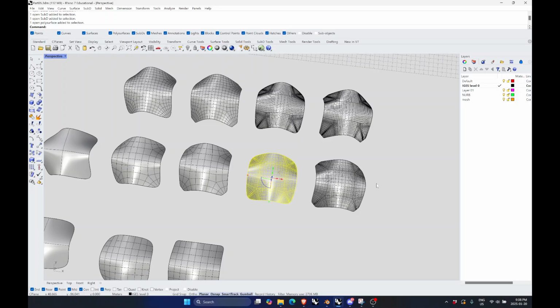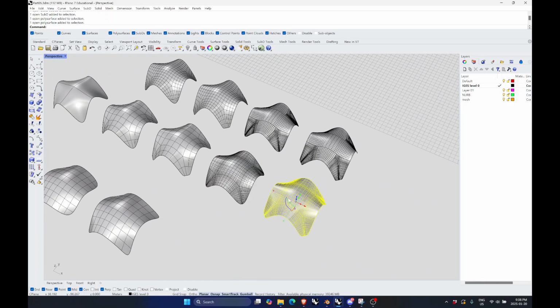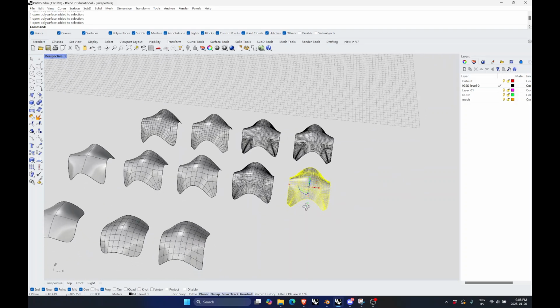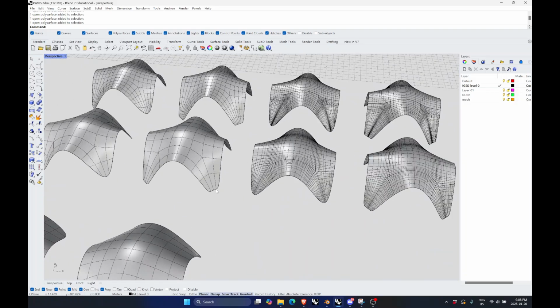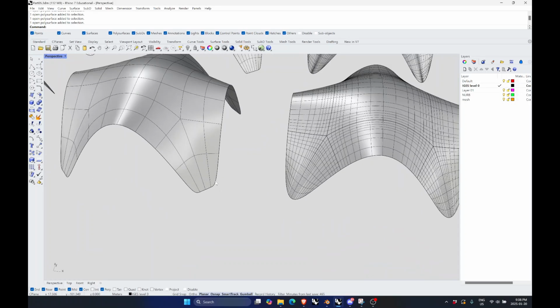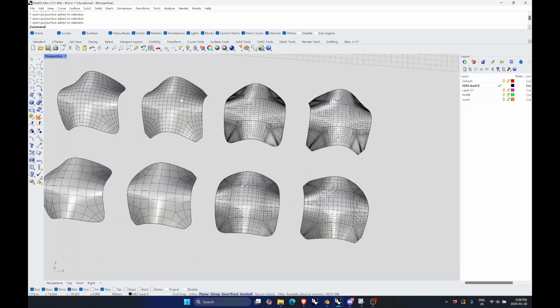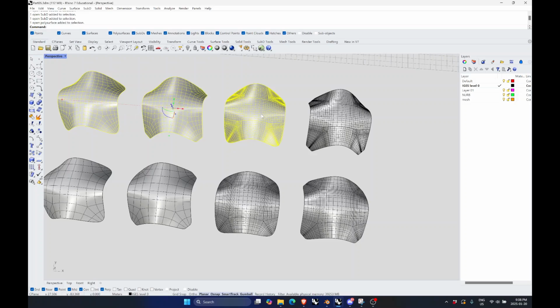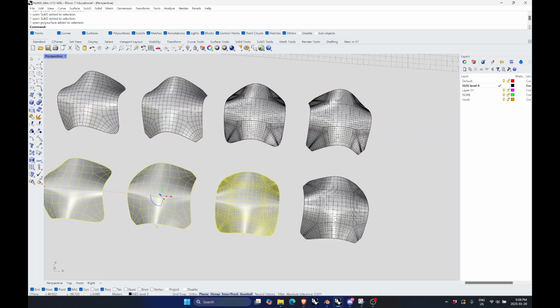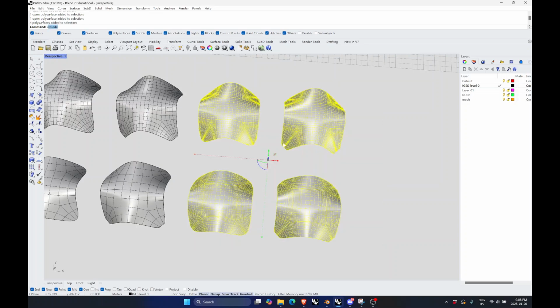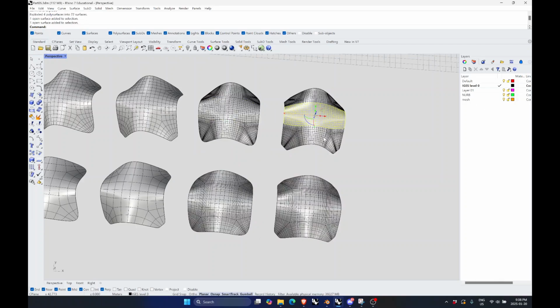So anyways, let's have a bit of a comparison. I've got these two geometries here. As you can see, when I wanted to keep corners, it did keep it. It rounded the corners a little bit, but it did keep it for the most part. These here are level 3 subdivision in the viewport, whereas these are level 2 subdivision. Let's understand the topology. I'm just going to take these NURBS and explode. It divides the objects up.